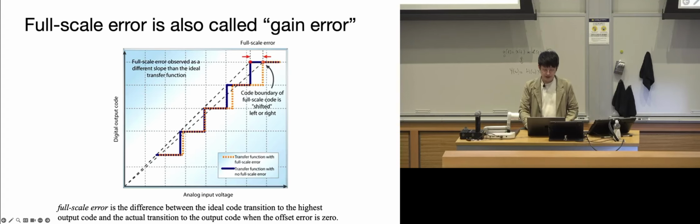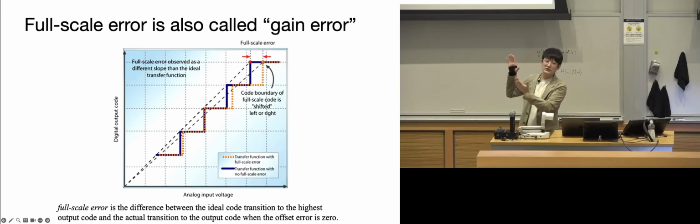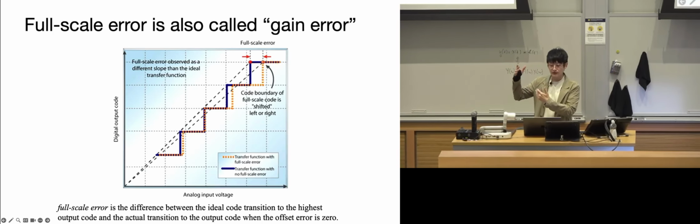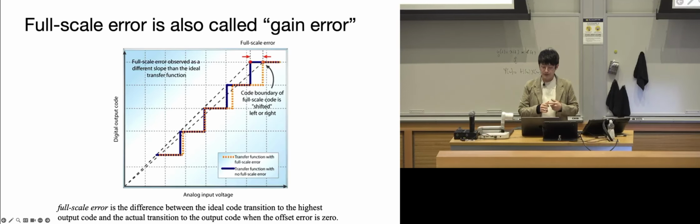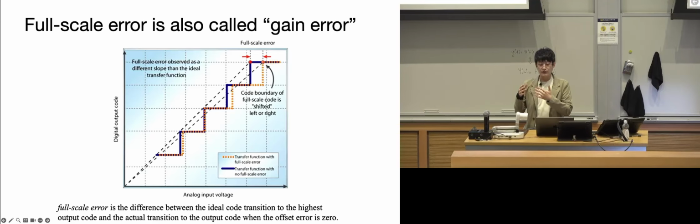We also have gain errors. This is when the actual output from the DAC and the desired output shift or vary, but proportionally to the amount of bits you added to it. So from the DAC's perspective, you can think of it as the output voltage increasing at a wrong rate compared to the digital input for the DAC, but they are proportional.